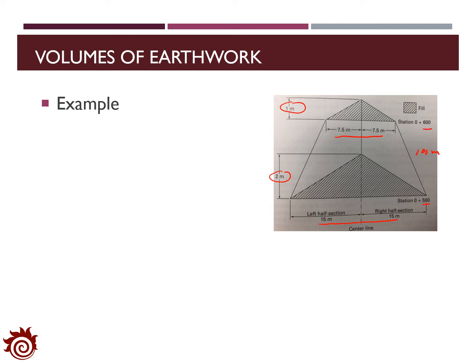Now, let's see how we can calculate the volume of the earthwork with the average end area method. First, we need to find out the cross-section area at the two ends.